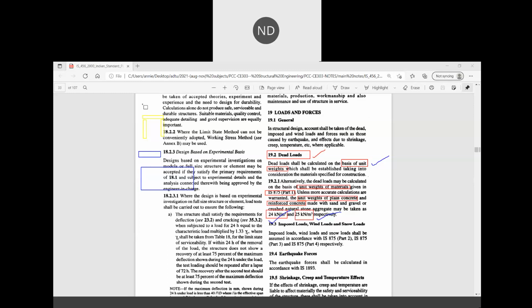अगर if you make another floor here, iska beam, column, beam, slab, plaster, paint, everything's load is going to be present permanently there until and unless you renovate your structure, or until and unless your structure fails or some damage happens. Until and unless these things happen, your structure will be permanently like that only. That means that much load will be only present for this column, for this beam, and for this another floor. If you want to consider again another floor, iska bhi load will be same, it is not going to change, right? So these are your permanent loads,